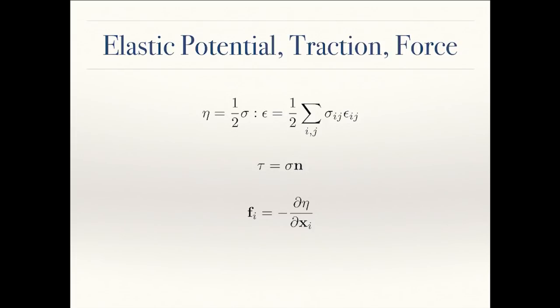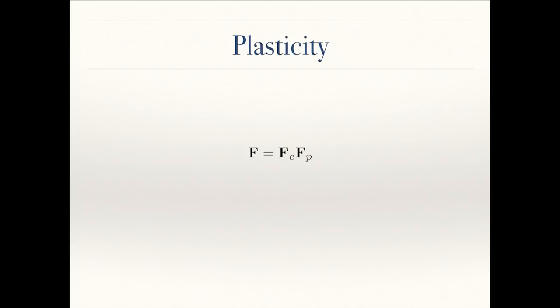We can define forces now. Given the energy, forces act to turn that internal elastic energy into kinetic energy. So they're in the negative gradient direction of that energy. So we take the gradient with respect to our degrees of freedom, xi, our positions, and that gives us what our forces are. We can also define forces as the integral over the boundary of some region of the stress times the normal. And this is actually in practice what people typically do because it's faster to compute.